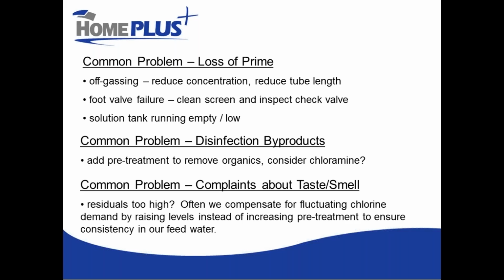So obviously our maintenance in keeping our solution tank topped up is important there. You could have a failure of the foot valve that allows chlorine solution to drain out of the tubing when the pump shuts off. So that's an opportunity to clean the screen at the bottom, inspect the check valve that's built into the foot valve there, and make sure it's operating correctly.